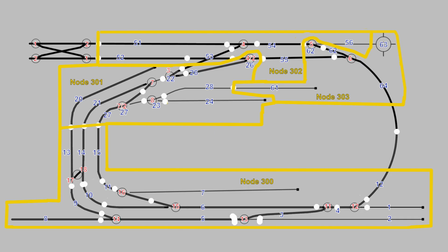But what happens if it doesn't? How do you go about fault finding? We need some practical way of looking at linking a particular section of track with a particular sensor, and that with a particular node, to make sure that the input to that node changes when a locomotive goes on it.